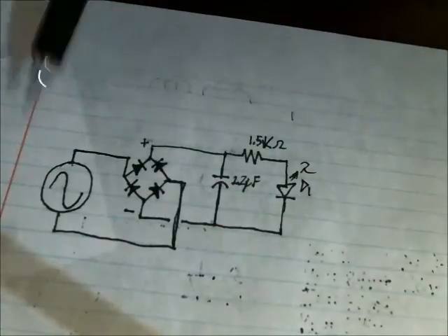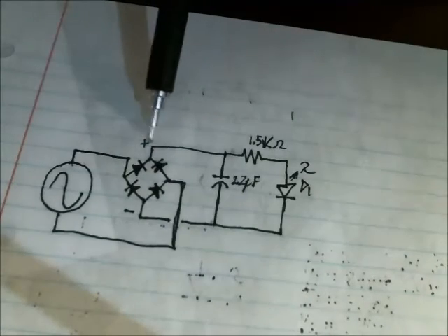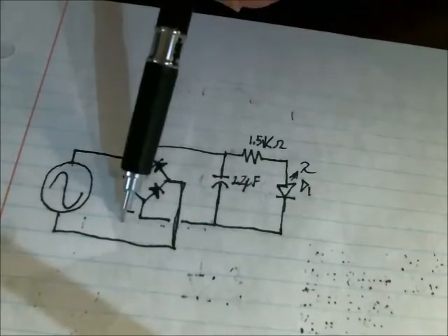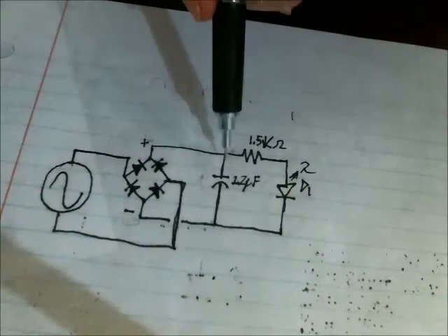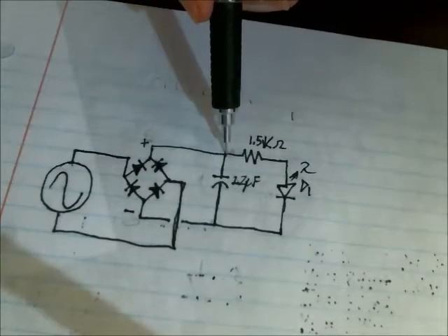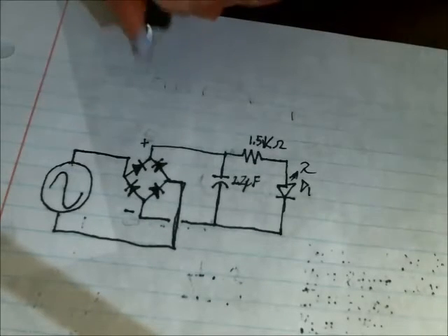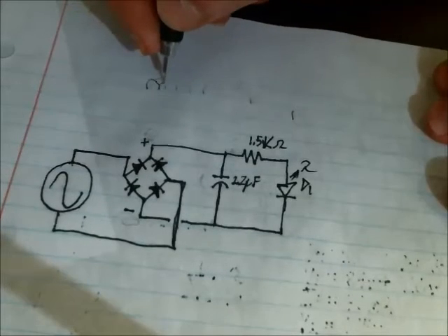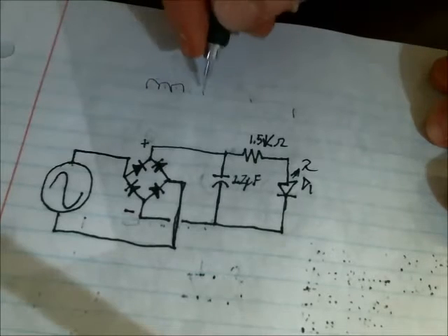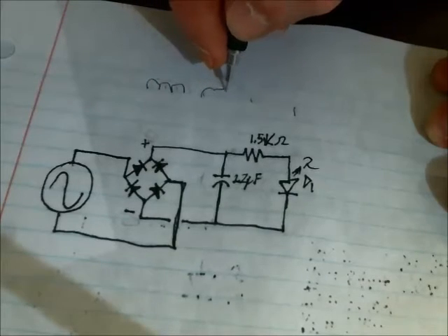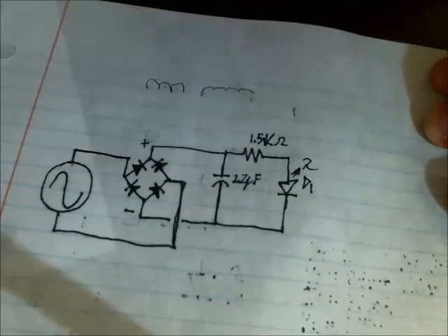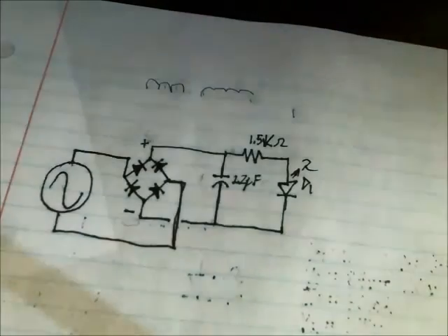And here's the circuit I'm going to make. Here's the bridge rectifier, here's the positive voltage off that, and here's the negative voltage off that. I have a capacitor placed from the positive to the negative, and that's just to stabilize the pulsating DC. So instead of having a signal that oscillates like this, it's going to be more of a stable waveform, like so. It doesn't reach the 0 point again.